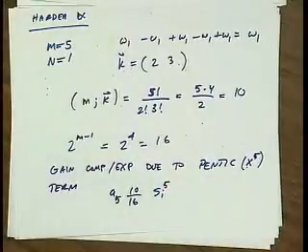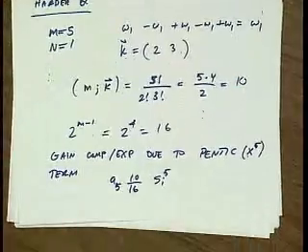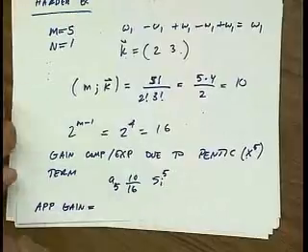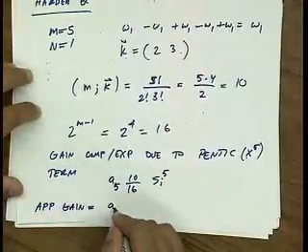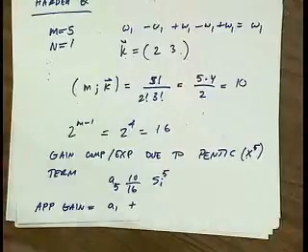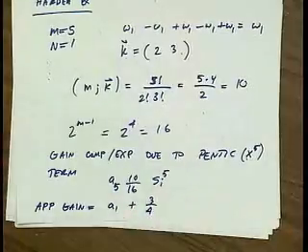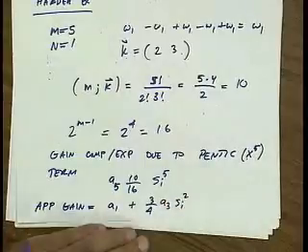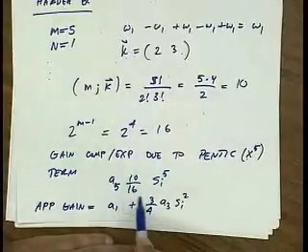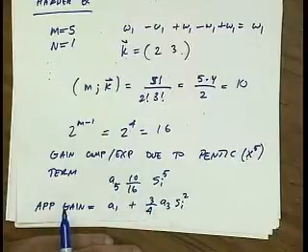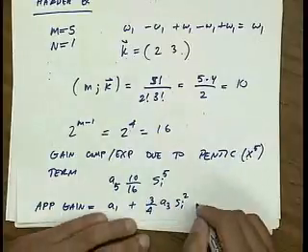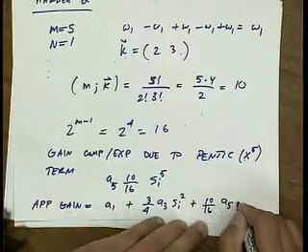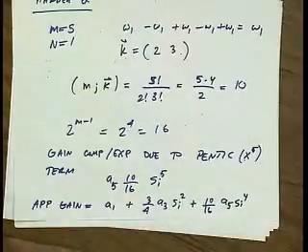Okay? So if I go back and look at the equation I derived last lecture for the apparent gain, last lecture we included the cubic nonlinearity. So last lecture we found that the cubic nonlinearity adds 3/4 A3 S input squared. And if I take this term and divide it by A1, if I divide this by S input, I get an additional 10/16 A5 S input to the 4th.